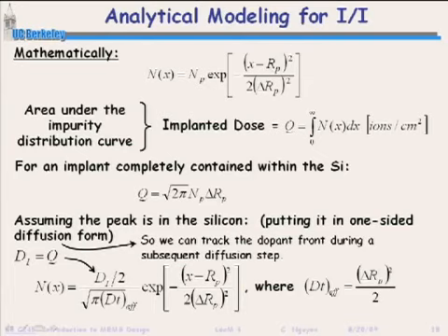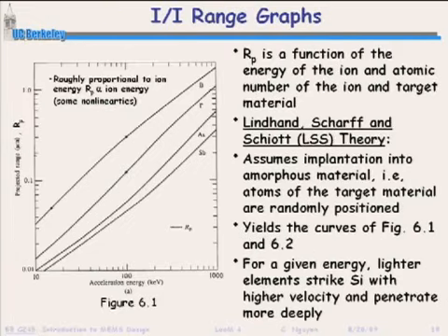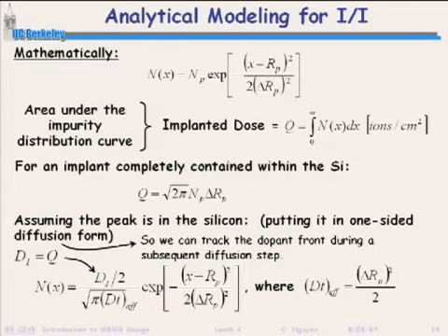There are graphs, so in essence, it's not as simple as this Gaussian distribution is showing. There's actually the possibility to have a lucky ion. If you look down at the crystal lattice, you can have tunnels or so, right? Depending on what your surface is, 100, 111, that sort of thing. You could have tunnels where there's some ions that can go in and never hit anything for a long time, which means that this Gaussian curve may not be right. You may have to have this curve and then have a trailer in this curve that lasts longer. So maybe the curve,